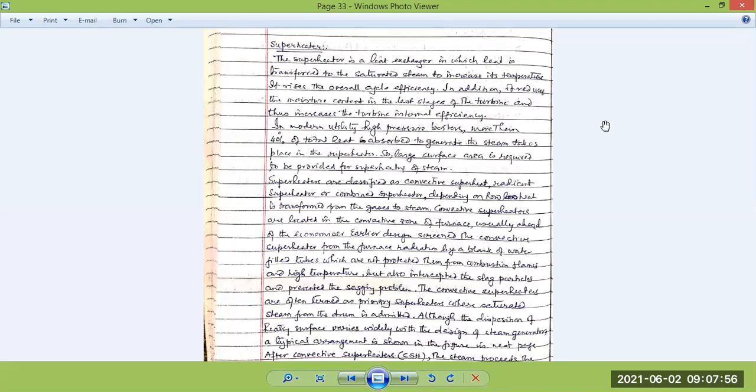So in a modern high utility turbine, steam of a considerably higher temperature than the boiling point is supplied from the heat exchanger, and in the turbine that heat is converted into kinetic energy, in terms of the high velocity of the fluid, which is increased on the turbine blades.